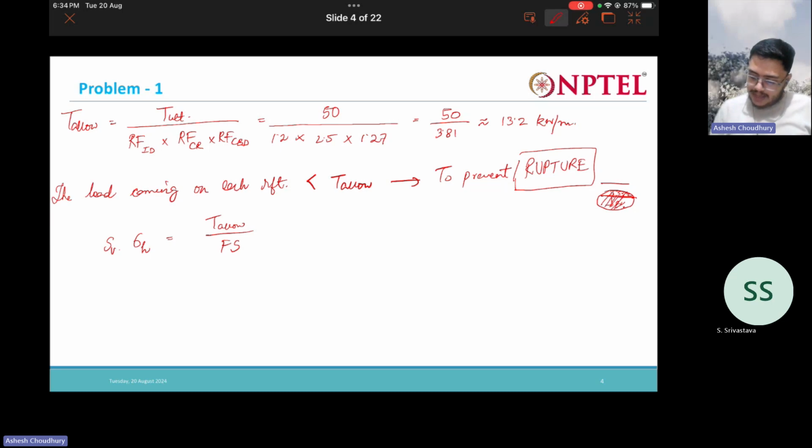This is the reinforcement, and sigma h is varying something like this. Now what we do, we take this much area, SV, so up it's SV by 2, down it's SV by 2. So what we are doing ultimately is just averaging it.